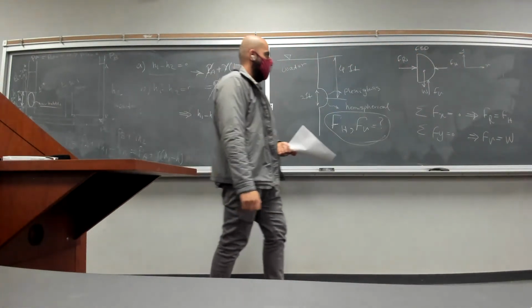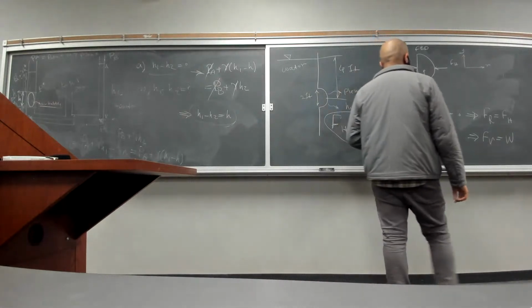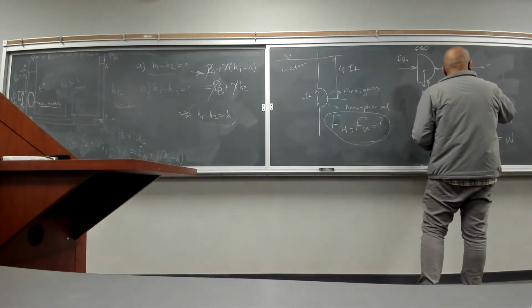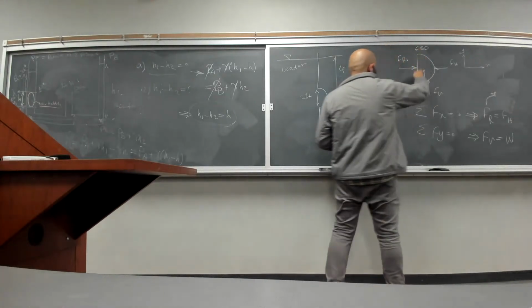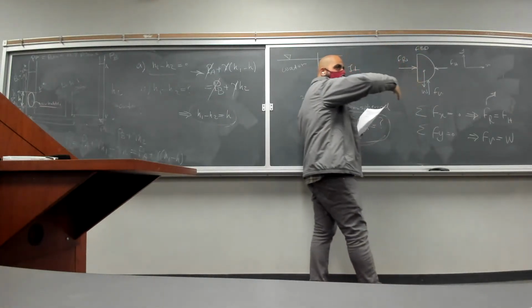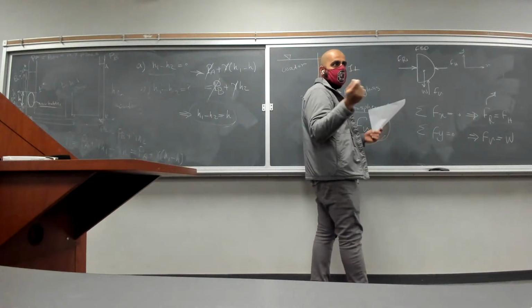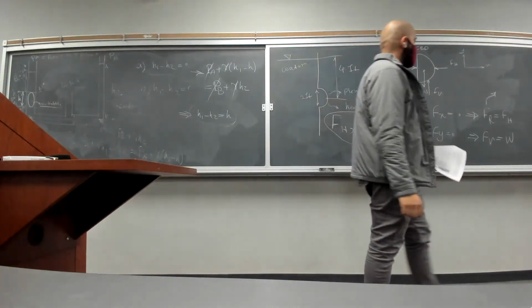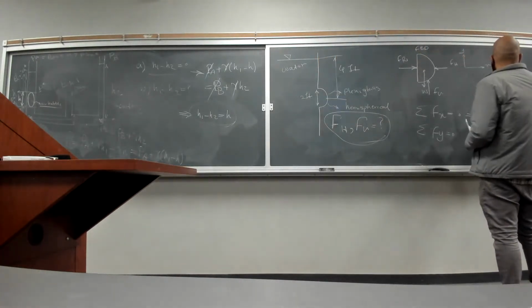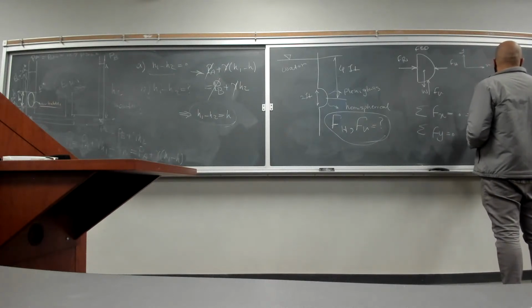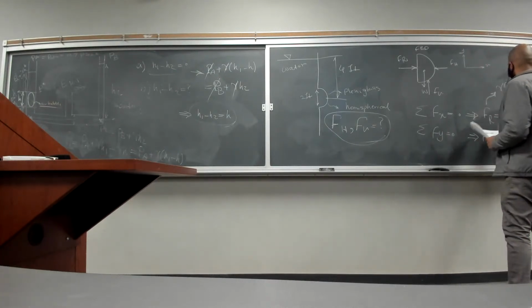How do we calculate the force of water here? That's essentially the hydrostatic pressure force on just a regular vertical wall, right? And we have already seen those. You essentially have to find the equivalent hydrostatic pressure multiplied by the cross-sectional area.